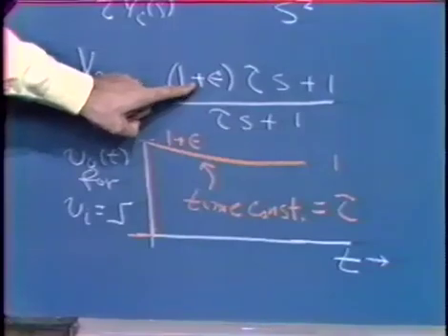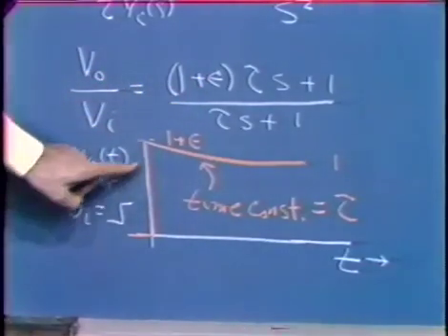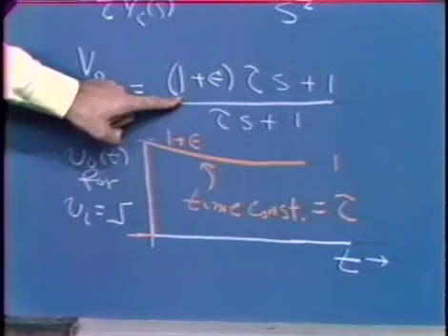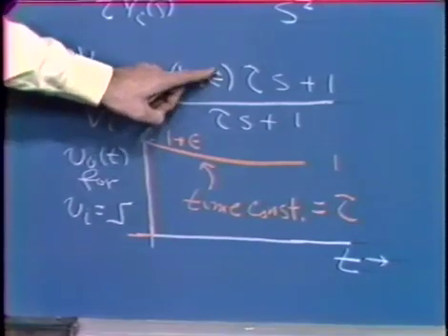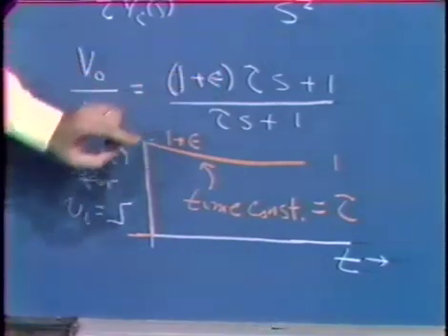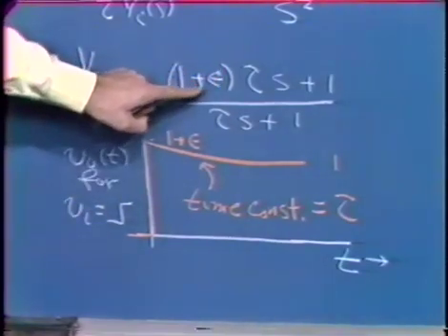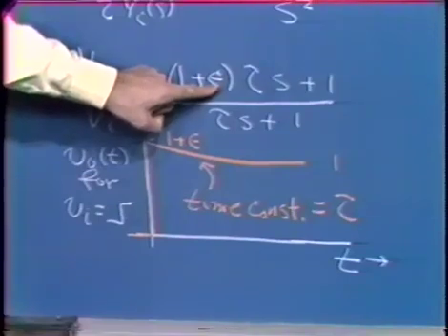Well, the step response of this transfer function is of the following form. This is basically the uncompensated or the overcompensated scope probe. If you adjust the transient response of a scope probe, what you're really doing is trying to get a pole and a 0 doublet to cancel each other. So this is the case where we haven't perfectly compensated the scope probe.